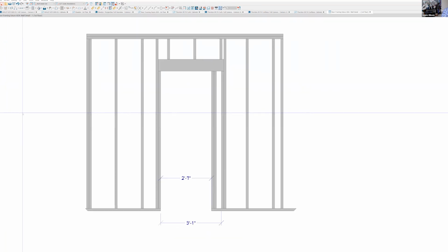So opening up this wall detail, I just overframe. So the header is large enough for a 3.0 door, but a lot of people don't want 3.0 doors going into their bedrooms or their bathrooms. But by overframing this way, as long as there's no electrical in this space right here, you bring a 3.0 door on site and cut the bottom plate, and you don't even have to repair any drywall. So it's that easy. So just a little thing that I tend to do, especially if I am doing a project for anyone who's at all older.